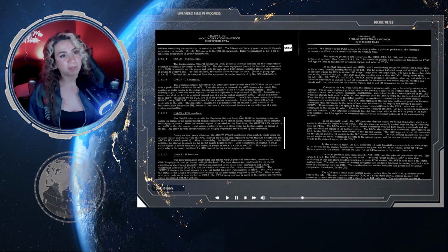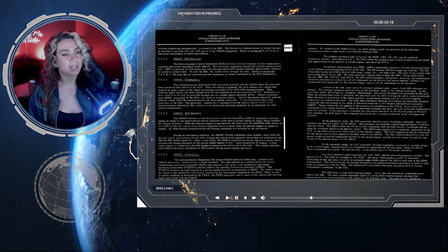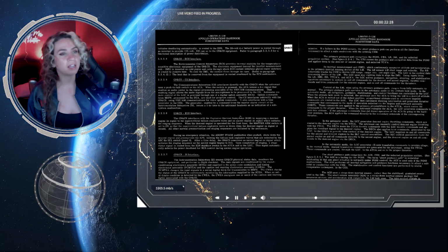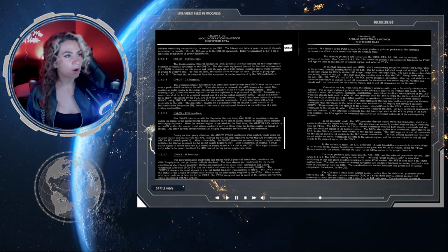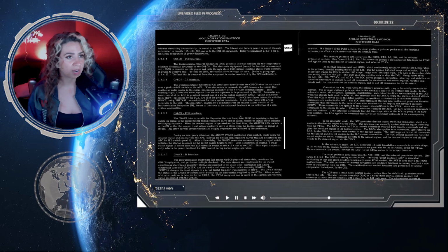Which continuously measures altitude and acceleration, is the primary inertial sensing device of the LM. The LR senses LM slant range and velocity. The RR coherently tracks the CSM to derive LOS range rate and angle rate.